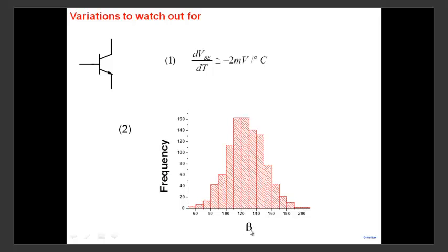If it's very sensitive to beta, then I want my transistor to be biased at, let's say, 1 milliampere, and you get 1 milliampere at a beta of, let's say, 100. But when beta goes to 200, you get 2 milliamperes. Or when beta goes to 50, you get half a milliampere. If the current would change in that manner with beta, then the whole biasing point is affected, and the whole transistor performance, the whole amplifier performance, is also affected here.